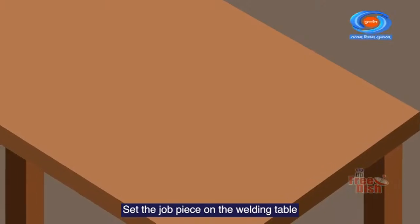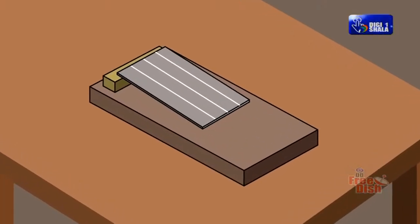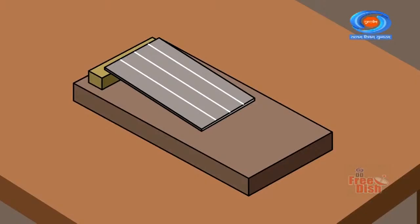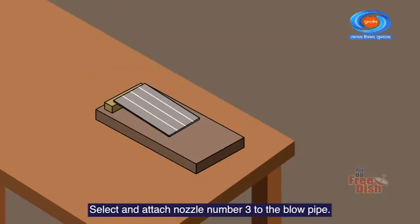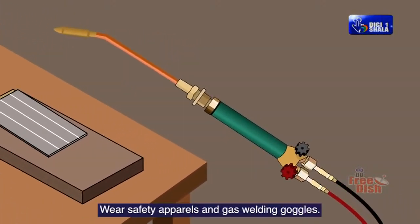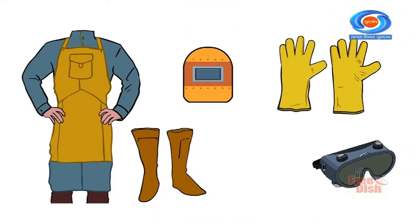Set the job piece on the welding table in flat position with fire brick support. Select and attach nozzle number 3 to the blowpipe. Wear safety apparel and gas welding goggles.